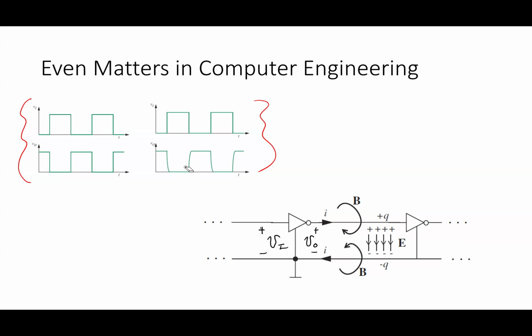Well, specifically the reason is it takes time to change states. The inverter is connected to the next inverter in this particular case. And so there's current that runs down that wire, goes through this thing, and then goes back this way. So ultimately, there ends up being some capacitance inside this. It's made with chips, and there ends up being a capacitor basically inside this chip. And so I could model this thing and say that there is essentially some element of capacitance from here to ground.